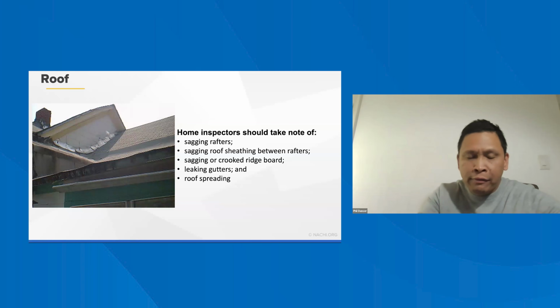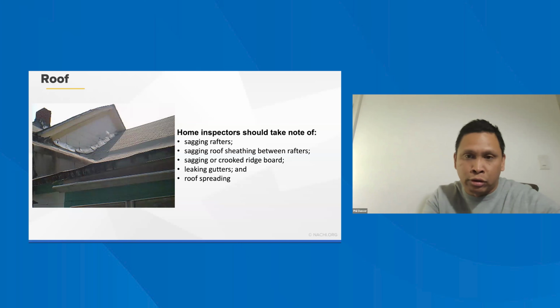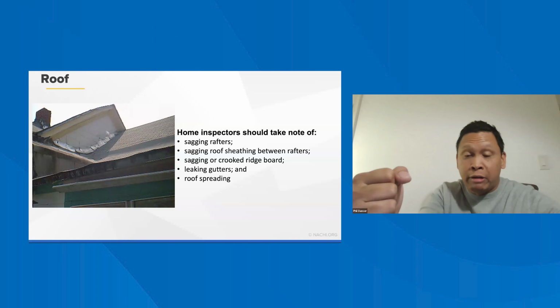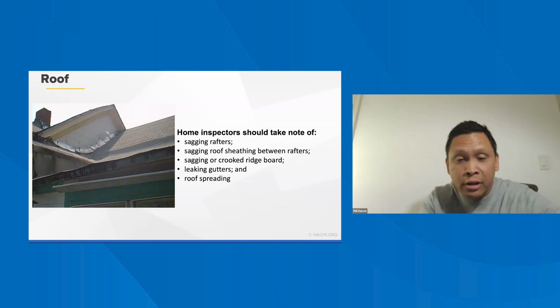So very, very important, because that whole entire system is being held up either with rafters or the actual trusses themselves. Which is also the reason why there are tolerances. That question that we got earlier, where the web framing would look like it was gapping or pulling away from the top chord of the truss. There's a reason why there are tolerances.